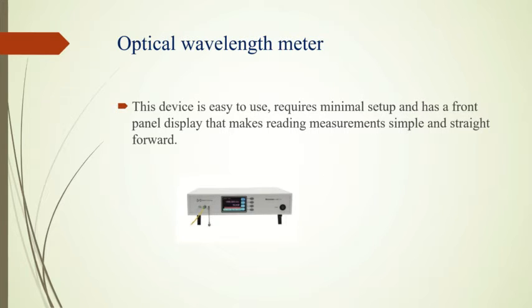Then finally, we also need to know the various types of errors that affect our measurement accuracy. We have wavelength drift, and that is usually caused by drift in temperature. Second, we have imperfections or changes of the beam profile, and then finally we can have fluctuations of the input power, and then detector noise.